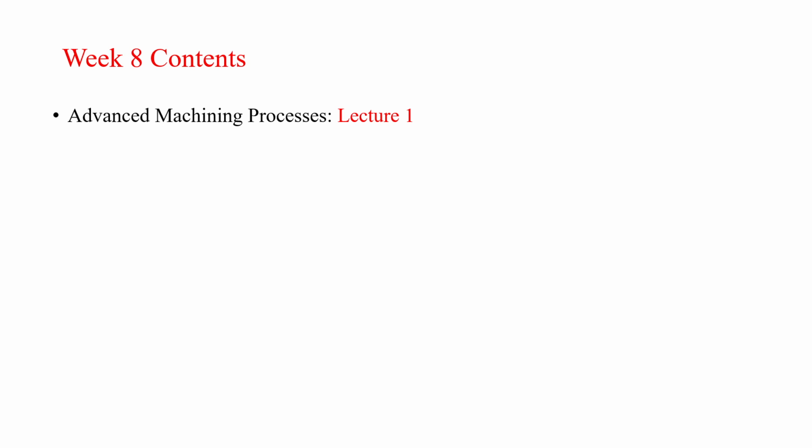Because of that contact, various limitations come up. It affected the workpiece finish. It affected the tool properties, tool geometry, tool dimension, even tool wear. It led to high tool wear. So all these problems originated in case of conventional machining. Therefore, to reduce this type of issues, there was advancement in the machining process, which is called advanced machining process or non-conventional machining process.